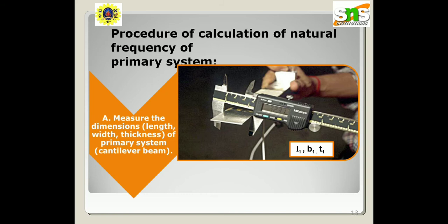An important measurement is the ratio of the force on the motor mounts to the force vibrating the motor. This assumes that the system is linear, so if the force on the motor were to double, so would the force on the motor mounts. The blue line represents the baseline system with a maximum response of 9 units of force at around 9 units of frequency. The red line shows the effect of adding a tuned mass 10% of the baseline mass.